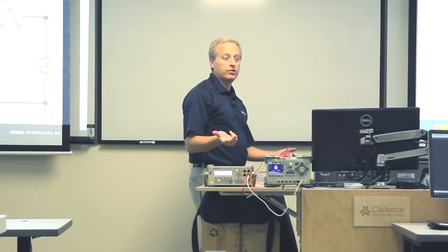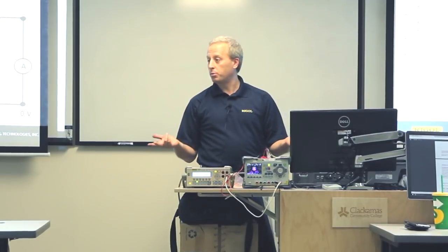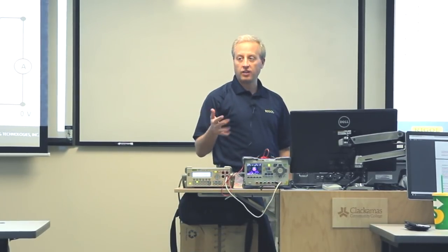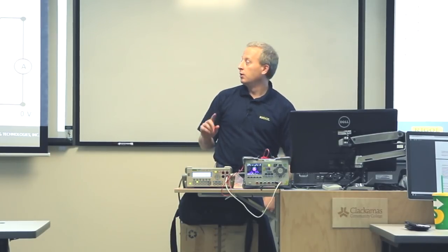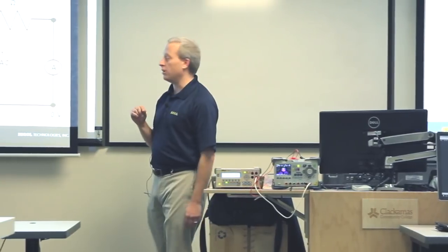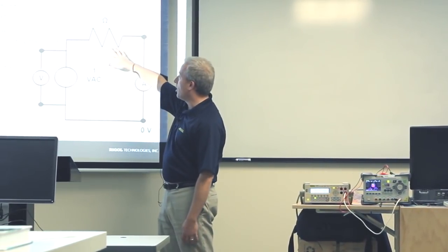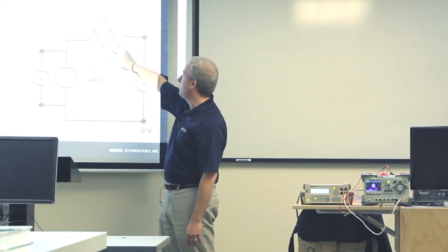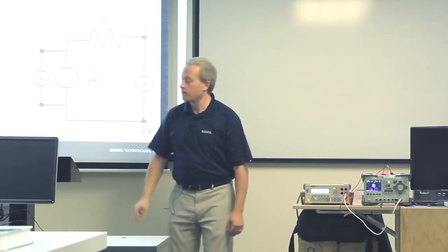Now, an oscilloscope, the standard passive probes, would still be called high impedance probes, but they might have an impedance typically of about a megohm. That allows you to make some different measurements with them. But in a circuit like this, it could also cause loading, because it's only a megohm, and if we had a megohm here, the current would flow evenly. So here we said we have about 100 ohms, so we're probably still okay if we did that.